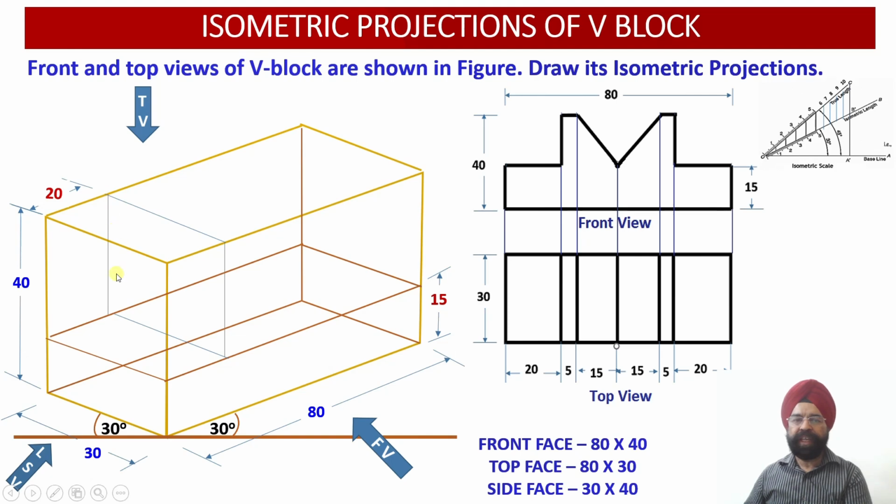So I have moved vertically downwards, and then this web from the top view I can see it starts from this point and it goes parallel to this edge. Please check. This edge is parallel to one of the elements of this web, and this is also parallel. Similarly, this is also parallel to the side view edge over here. Similarly, these two edges of the second web are also parallel to the side view elements over there. So with respect to this x-axis, that is where we had mentioned this 30 millimeter.